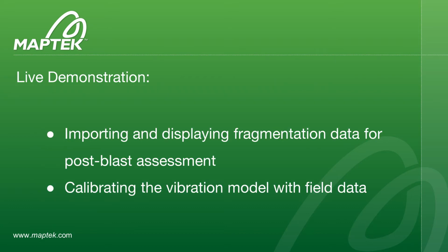During the webinar today, I will cover 2 practical examples. Firstly, I will import some field measurements for fragmentation, and then give some examples of how this data can be used, displayed, and tabulated back to per hole parameters. For the second part of the webinar, I will be looking at the vibration tool and add some additional data points to calibrate the model for a current tie-up design.